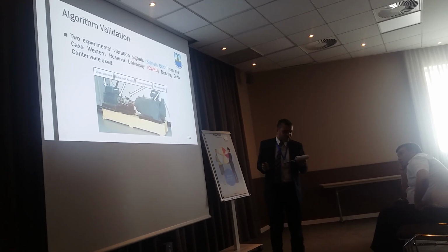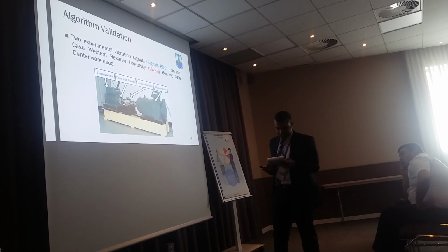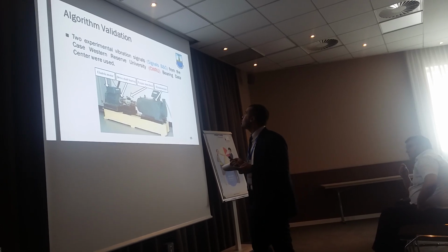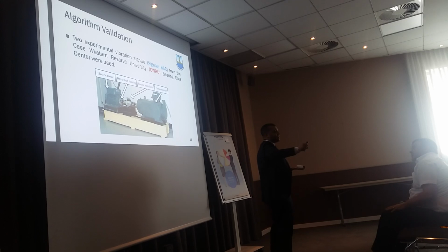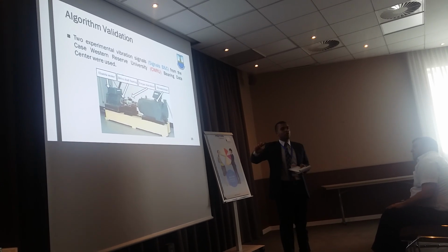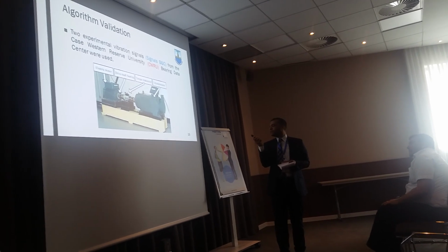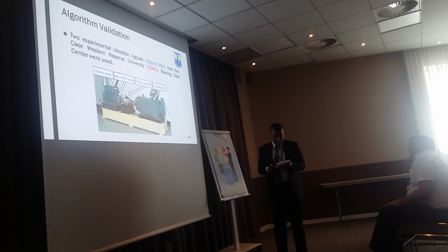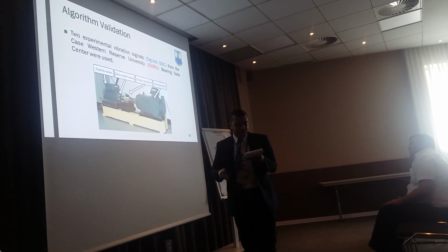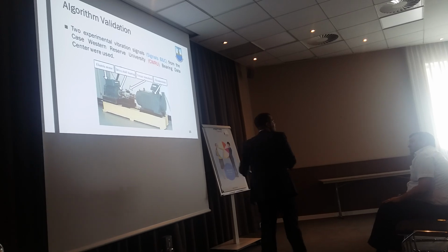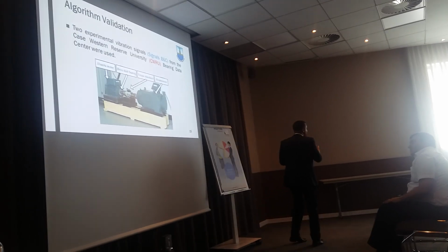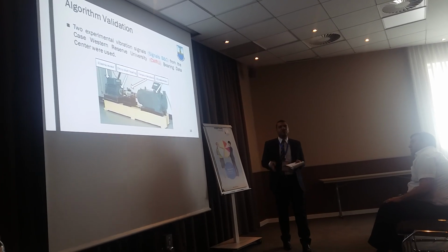The test rig consists of an electric motor driving a shaft in which a torque transducer is mounted, and they change the torque by this motor. Faults with different sizes were introduced separately to the test bearings. Every test bearing has an individual fault, and vibration data were collected.